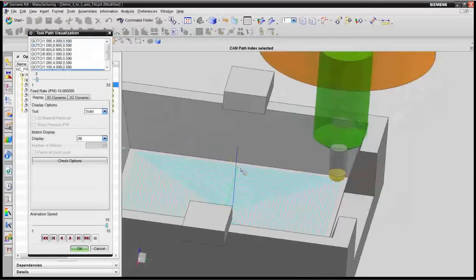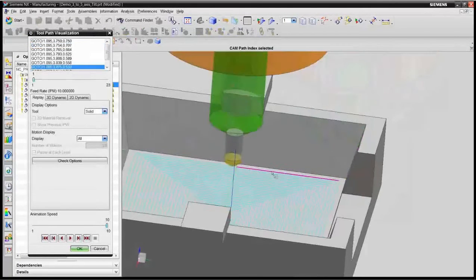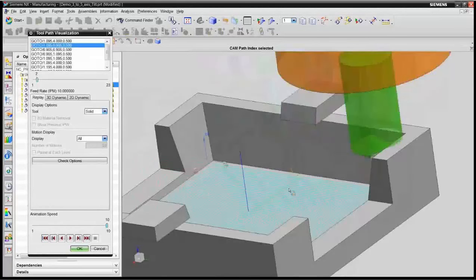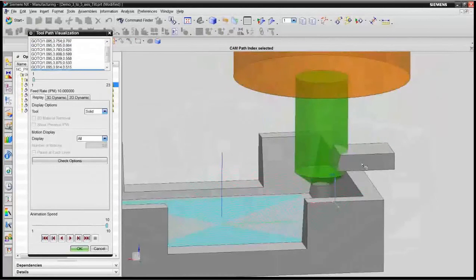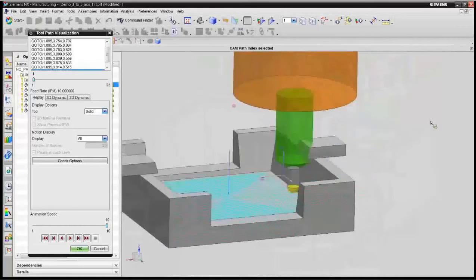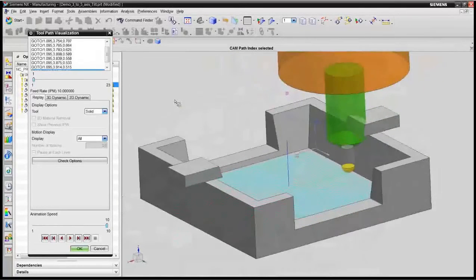Or also, if I come over, sorry, let me get all the way down here. So if we come over here, we're colliding with the clamps also. That is very undesirable. It's kind of detrimental to your machine tool life. But the advantage, we want to use a short tool to make it more rigid.